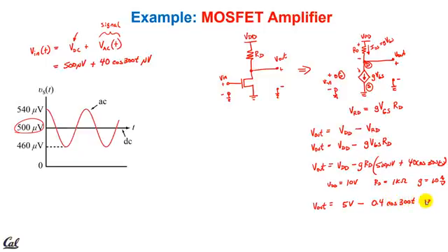Well, that's very interesting. At the output, it looks like we have our DC voltage that keeps us in saturation. Yeah. And then an AC voltage, which is like our amplified version of the input. Okay, we started with 40 microvolts and we ended with, well, looks like 400 microvolts. Yeah, so of course the frequency didn't change. We all know about that now, right? It's a linear circuit. And hopefully I did my math and you can see that this amplified up. The DC part amplified up again, and then we have to get rid of it.